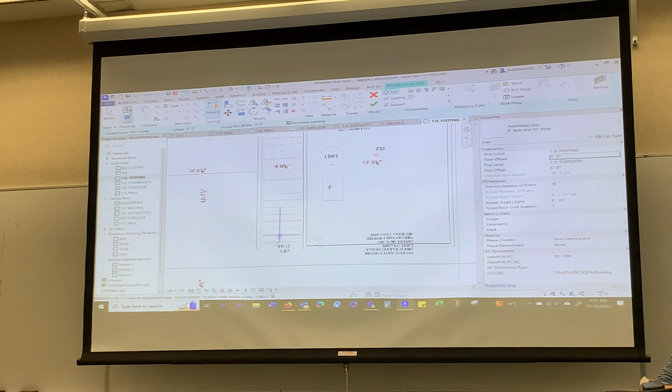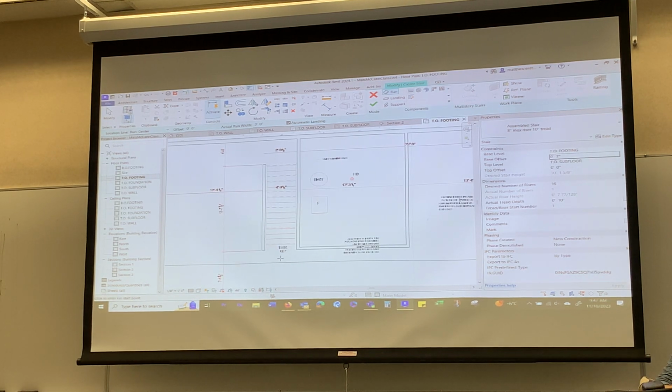Now, I can use the DWG as a good guide. I'm going to start way back here because I'm going to pull them into position later. So I'm going to start here, click, and I'm going to come up here somewhere. I'm going to click. It'll stop on you. You won't be able to drag anymore. So there's our stairs. Sorry, which line did you choose from the bottom? I just guessed. I didn't choose a line. I just placed it way past where I know it's going to end.